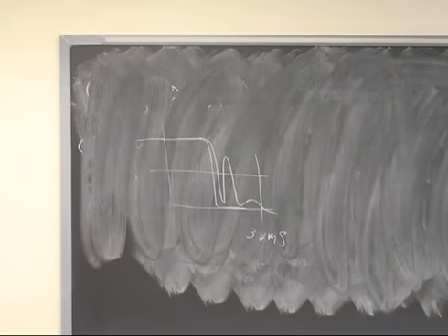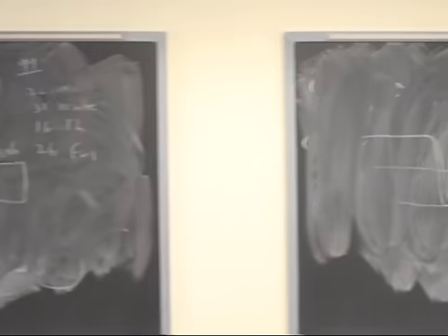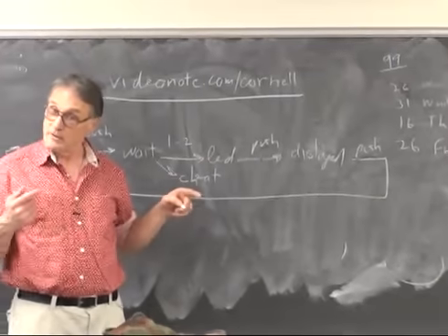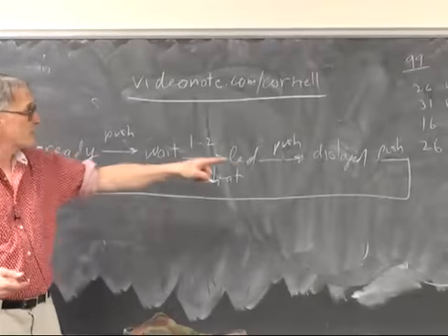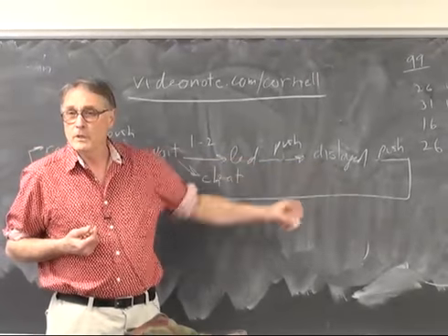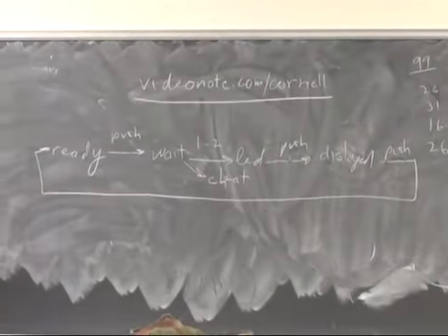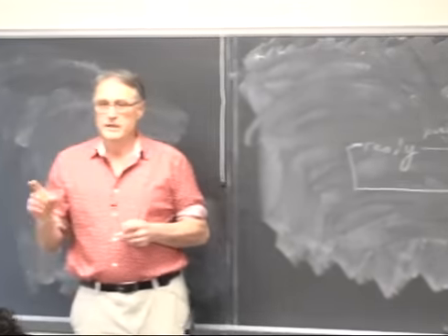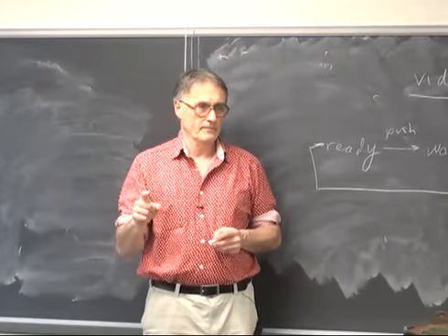So you push the button, you detect that it's come back up, but it's still bouncing. It hits again, and it falls through the loop, and you never see the displayed time. So you have to detect not only that the button is released, but that it stays released for 30 milliseconds.